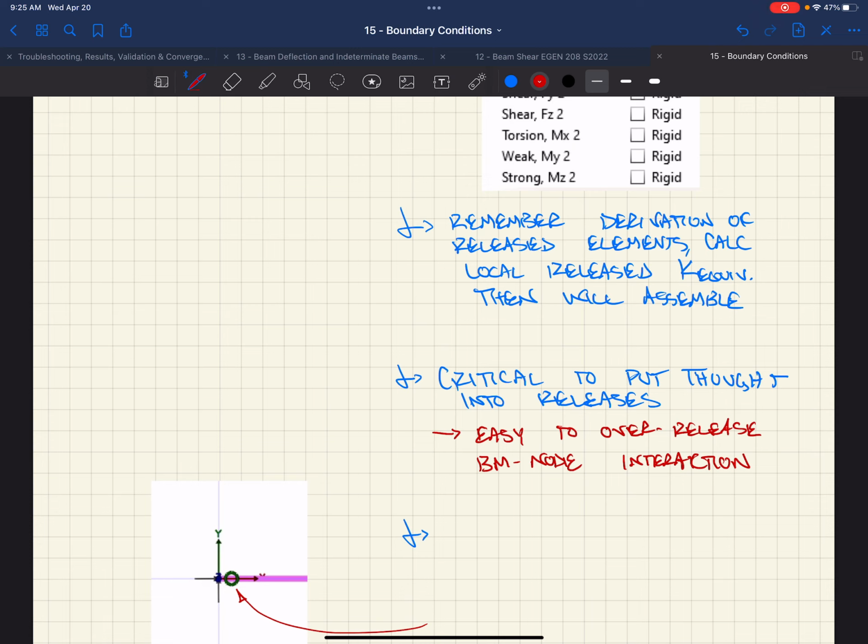If it was a hanging column, like instead of holding this girder up, you wanted a big lobby area and you're hanging this from up above, then again, I'd probably do a simple support there. If you had 2 of them doing something like this, I don't know why you wouldn't just run this continuous and then break the beam. And in that case, I would say that it's rigidly supported.